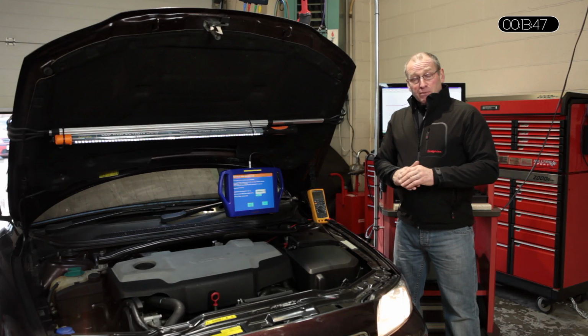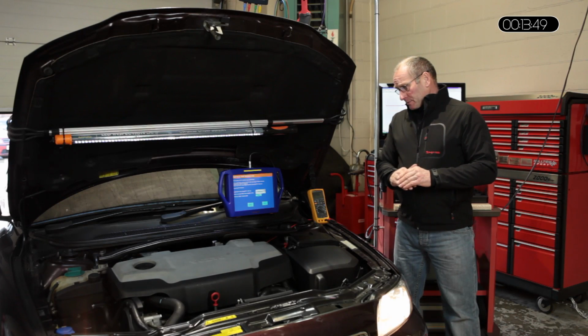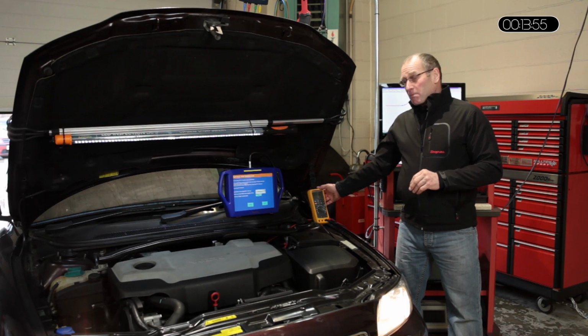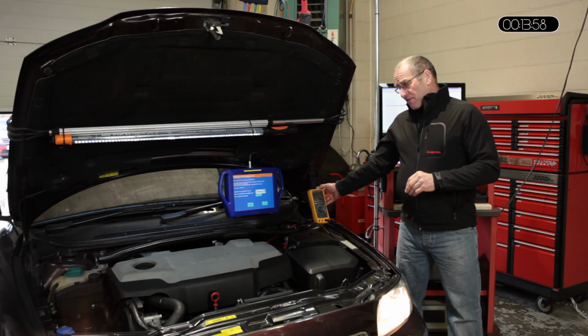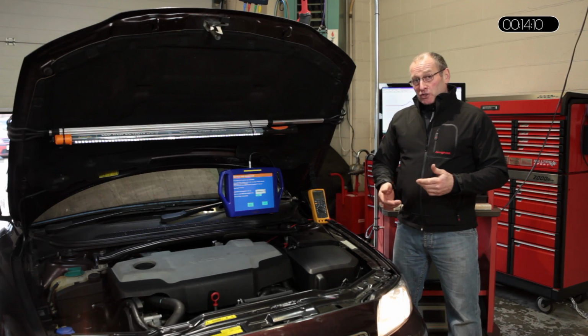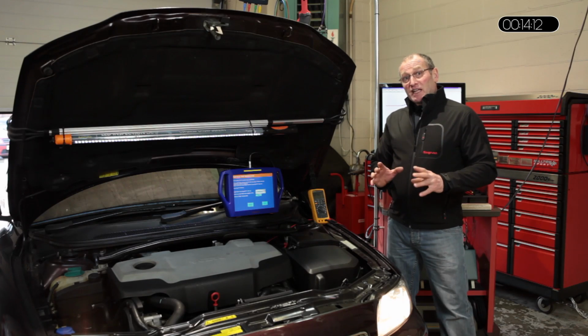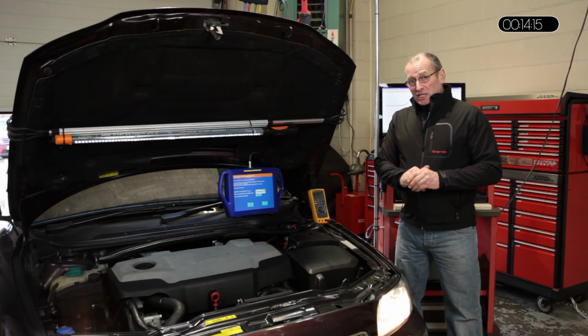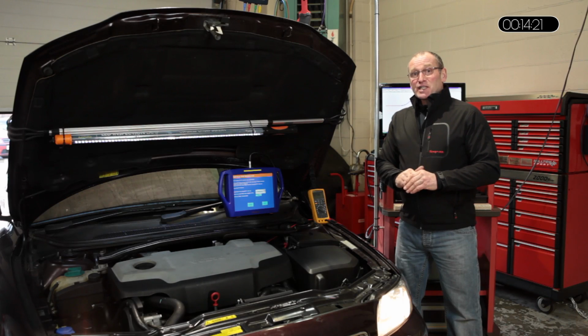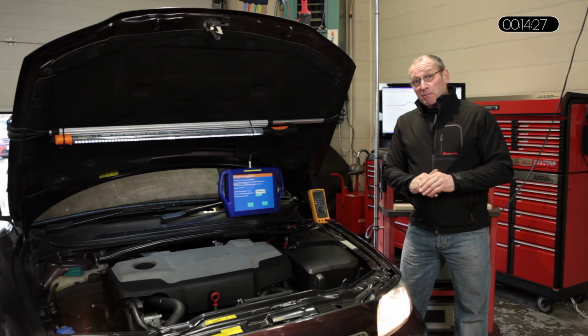The third process I'd like to look at, having dealt with the serial communication option, the multimeter, which is really a very simple option. It's a very easy task to connect just a multimeter to the DPF sensor, drive the vehicle, and basically you want to see no more than about 1.6 volts. If you see a higher figure than that, when you get to around 2 volts, 2.5 volts, you're definitely facing a partially blocked DPF. When you get to around 3, 3.5, 4 volts, you have got a seriously blocked DPF and probably beyond the ability to manually regenerate that DPF.